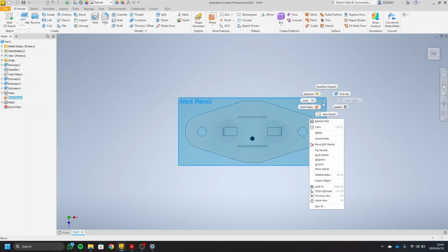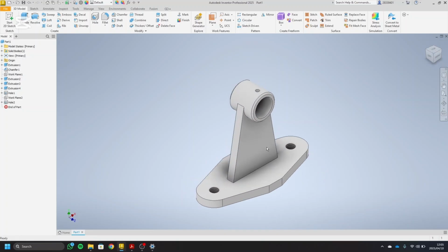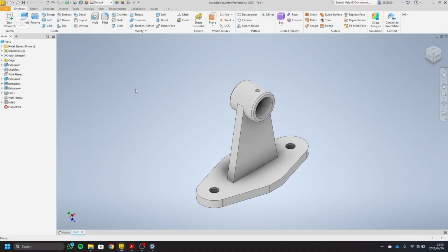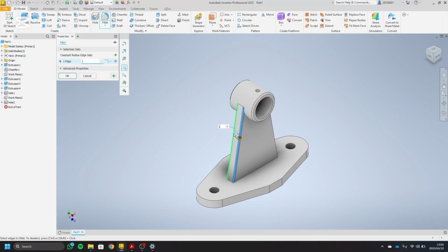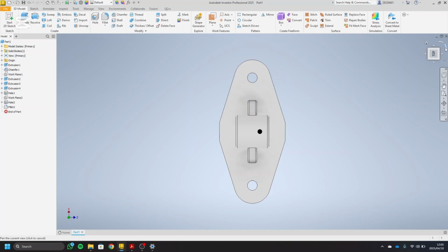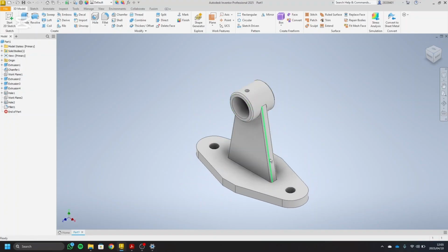Okay, so since that is done, now we can create the ribs, right? I almost forgot, there is a fillet on these edges over here. As you can see over here, it's radius 1. So let's go ahead and do that. So fillet of radius 1, so 1, 2, 3, 4. Right, there's the 4 fillets, and so that is most of the model done.